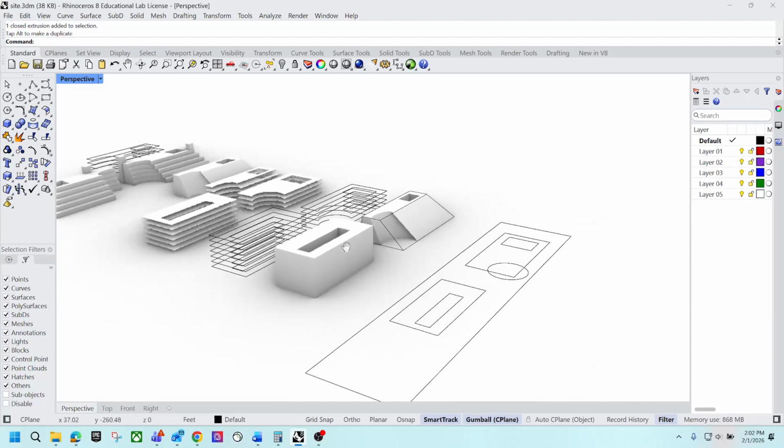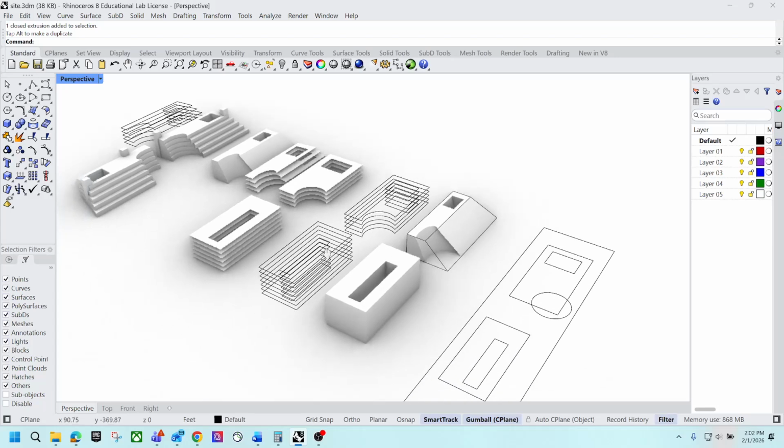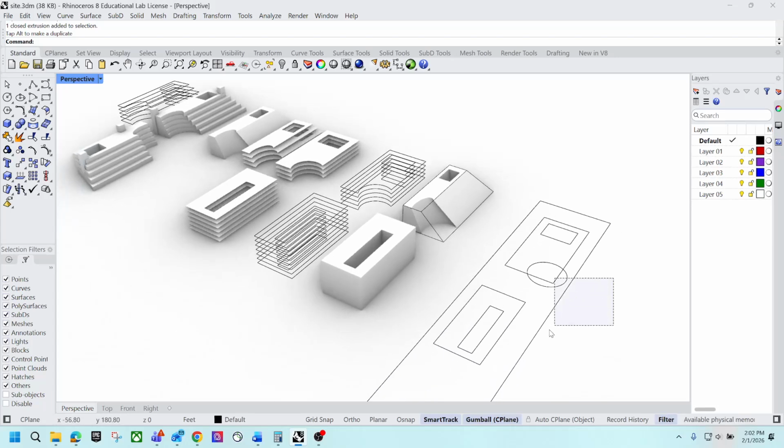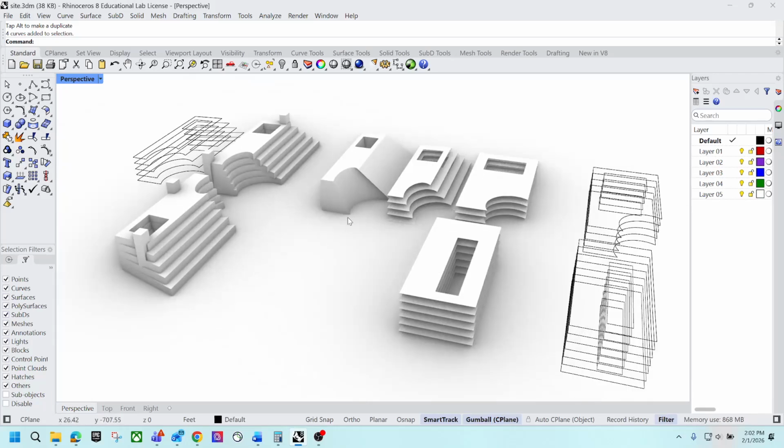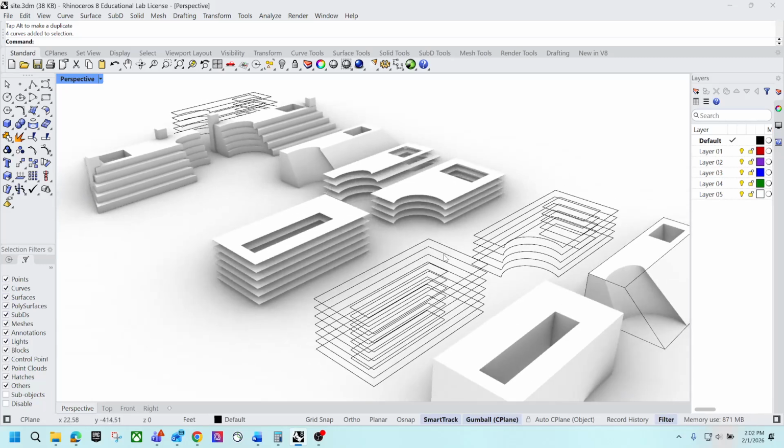All right, I think this is all for this super quick demo. Just want to show you the whole process. Start with curve boolean, right? Generate basic surface, calculate BCR, then you can extrude this into a 3D volume, and then you can do the contour, you can do planar curve, you can calculate the total floor area, and then you can calculate FAR. I might do another tutorial to show you how to do this in Grasshopper if many people are interested.